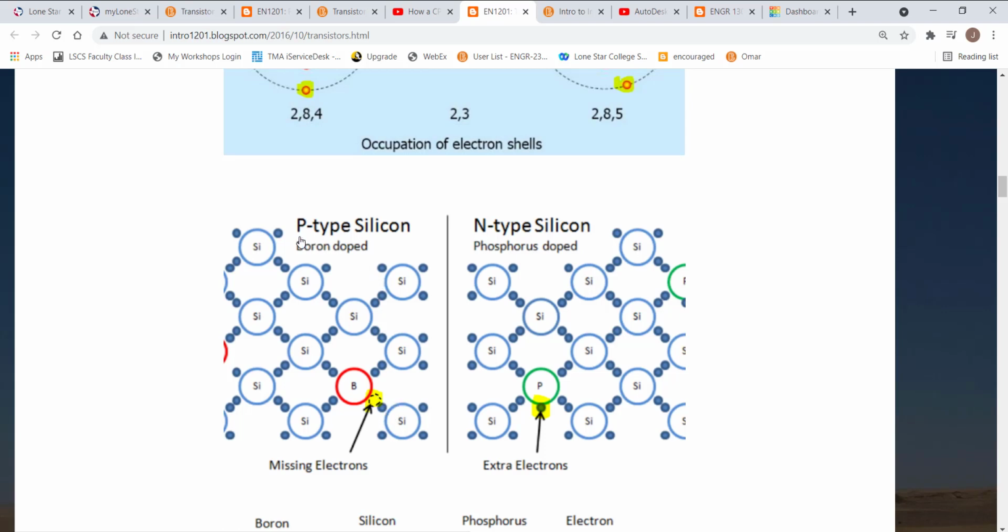So this is actually called a p-type material. It is not actually positively charged. If you count up the number of protons and electrons, they're balanced in this picture. But it feels positive because it wants another electron. It wants this electron not to balance charges, it wants the electron to balance bonding between the electrons.